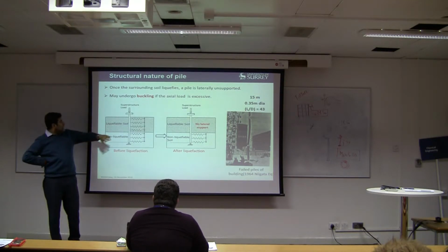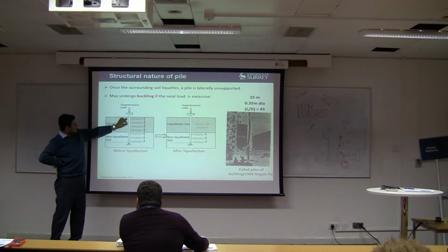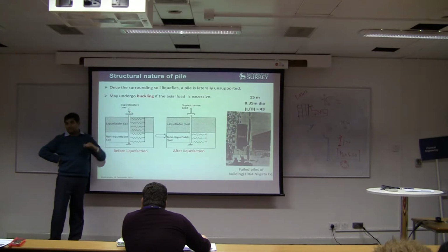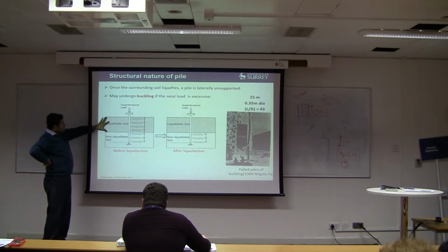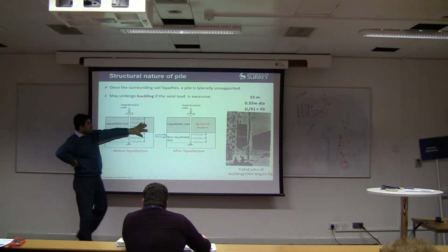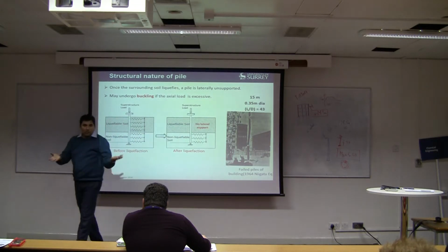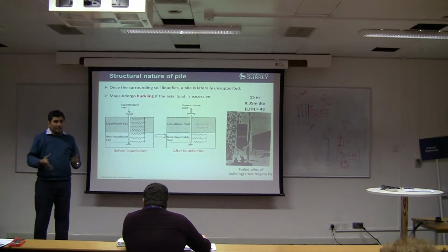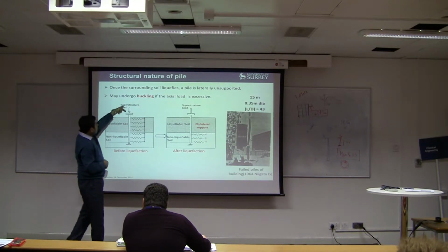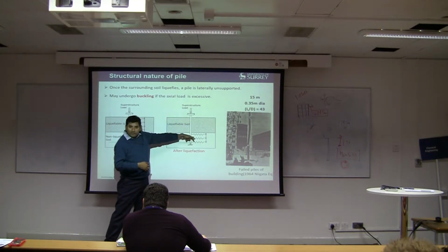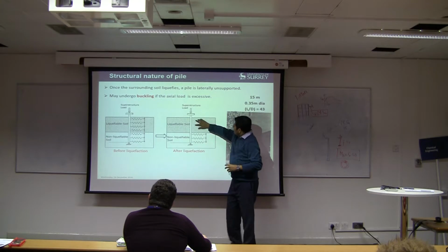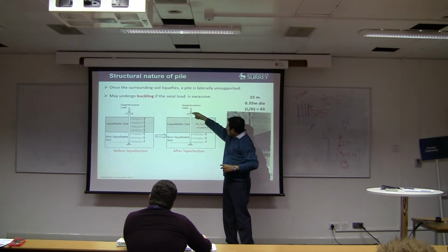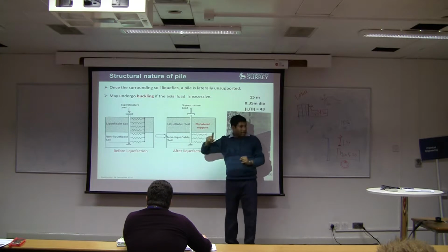If you have soil that is, say, clay, then sand, then stiff sand, then clay, and so on, you can model all of it by having different springs. Okay. Now, if the soil liquefies, this part you will have no springs, because what we're saying is that it does not have any support. Therefore, a vertical load will be completely unsupported. Right? Not only that, due to friction, this load reduces. What I mean to say is here is this.